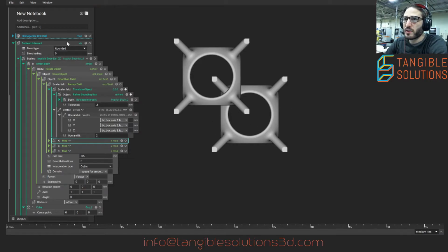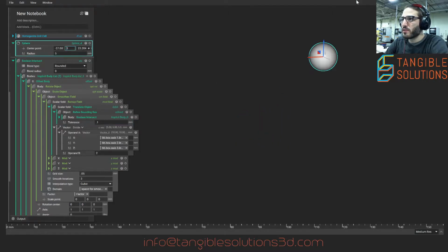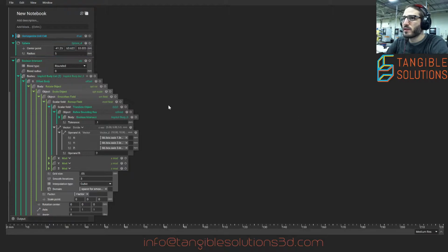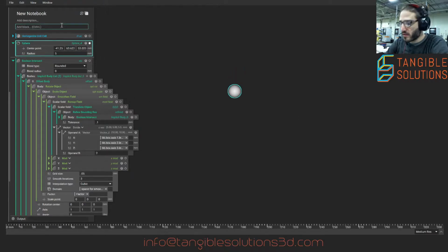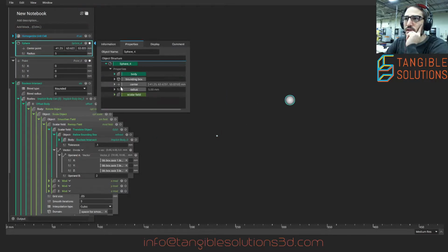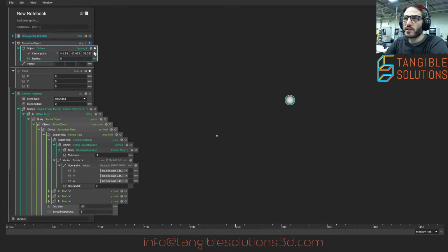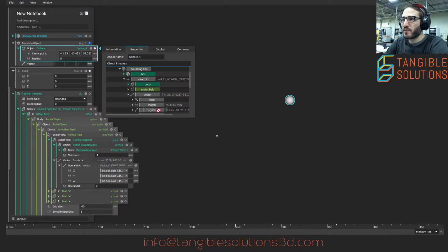If you don't build your unit cell here, I could show you a little bit of a trick. If you've got your unit cells way out here, it just happened to be off in La La Land over here, but this is my 0 point. What you can do is look at the center of your bounding box, or your centroid, and look at its vector. This is the vector that defines its center point, and so you can take this sphere and translate it by its negative vector, which is going to pull it back to that center point.